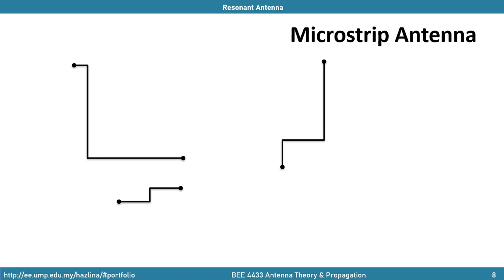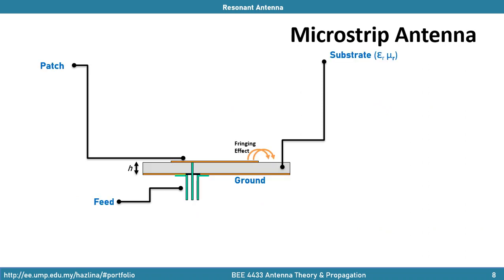Microstrip antenna is also known as printed antenna and usually means that the antenna is fabricated using microstrip techniques on a printed circuit board. They are most widely used at microwave frequency range. The structure of a microstrip antenna consists of a radiating patch, ground, and a substrate. Both radiating structure and ground are made of conductors. These two structures are bonded with a dielectric substrate.